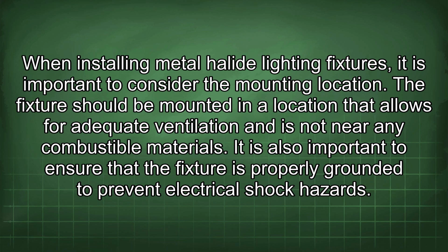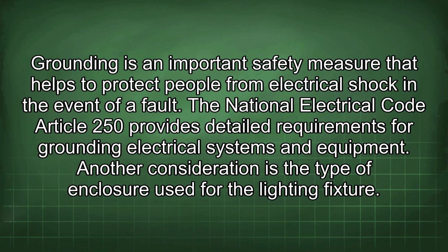The fixture should be mounted in a location that allows for adequate ventilation and is not near any combustible materials. It is also important to ensure that the fixture is properly grounded to prevent electrical shock hazards. Grounding is an important safety measure that helps to protect people from electrical shock in the event of a fault. The National Electrical Code Article 250 provides detailed requirements for grounding electrical systems and equipment.